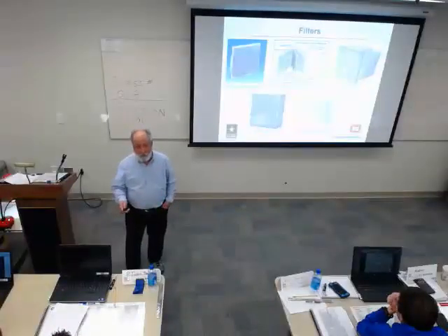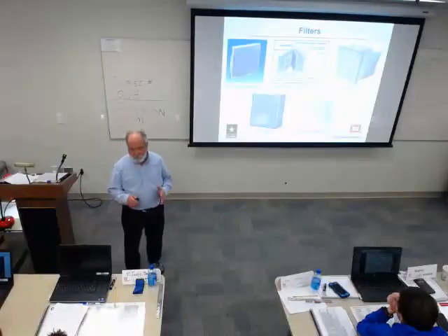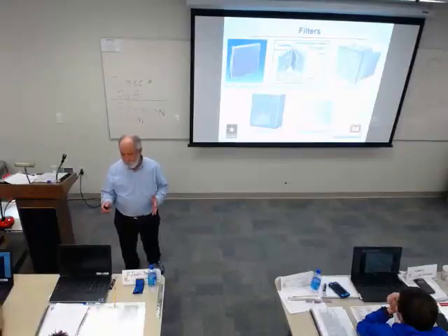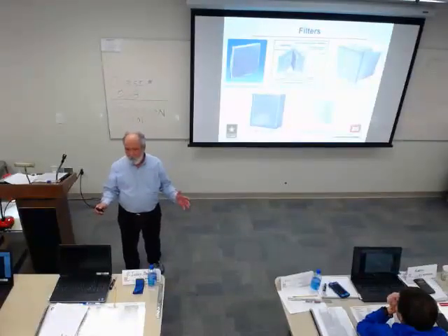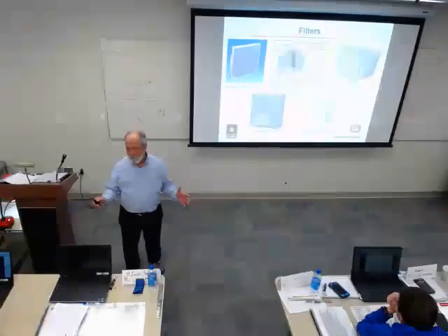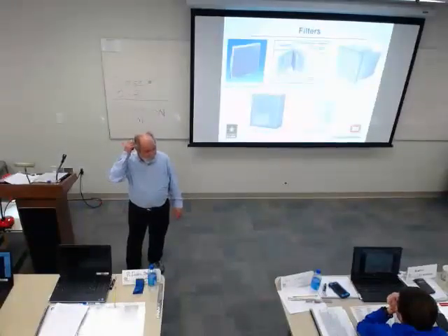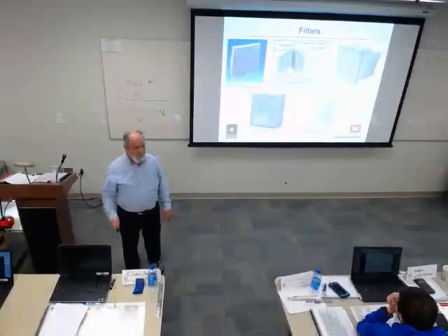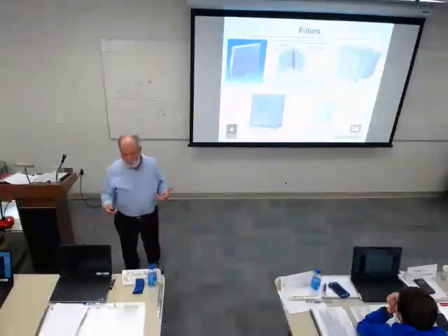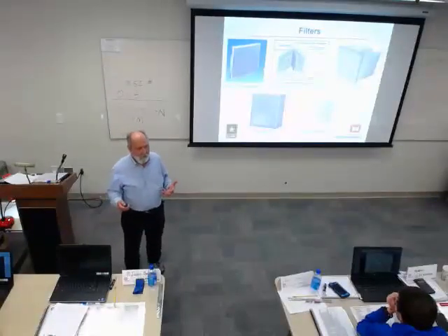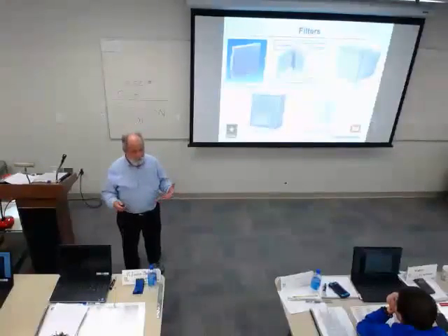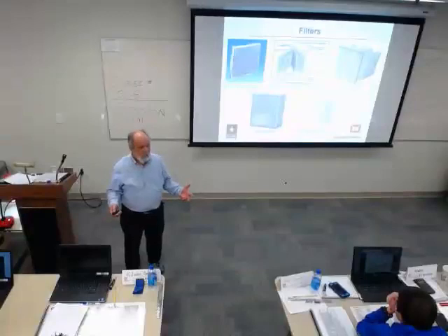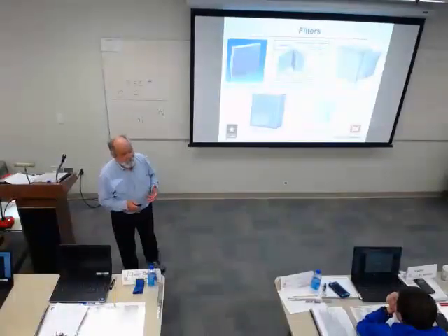So if I have, let's just say, 2 feet of filter, and I replace it with something that's got 4 feet of filter, I have just reduced my pressure drop through that filter greatly. Another thing I've done is increase the life of the filter, because I change filters at a certain pressure drop. And now, because my flow rate through the filter is lower per unit area of filter, I can carry more dirt before I get up to that place where I have to change it. So it's something to keep in mind.